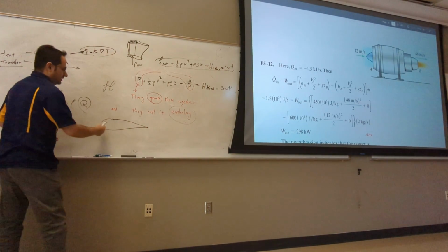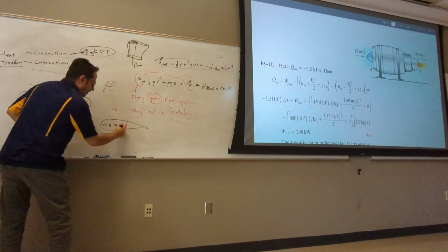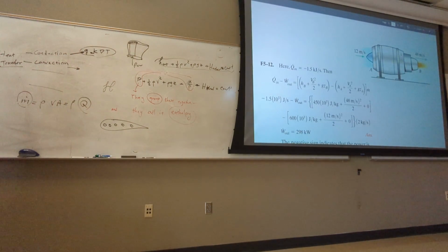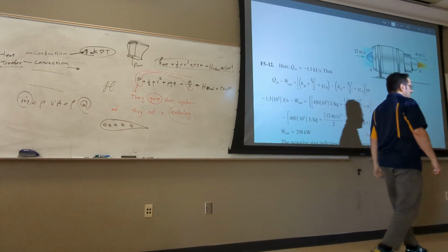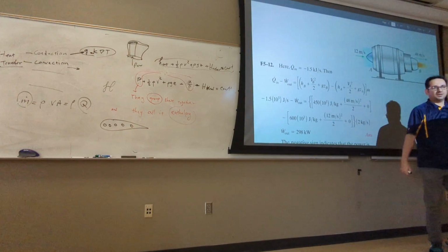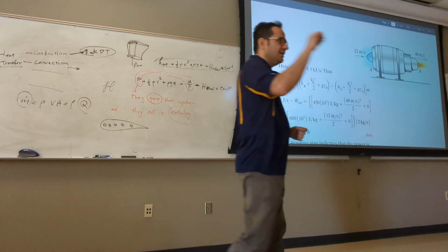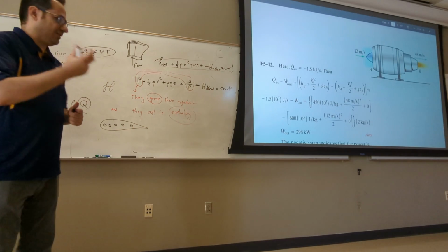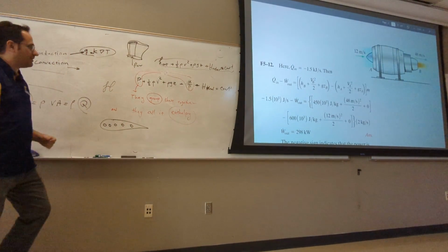That's your airfoil, the cut of this blade, we call it airfoil. There is something like a liquid pipe that goes through this to make it cool, because there is so much heat and pressure. And imagine how ridiculous it is to design that cooling system. Because you have deformation, it may break. The moment you put a pipe inside of it, you reduce its strength, right? The cross-section area will decrease, so you reduce the strength.